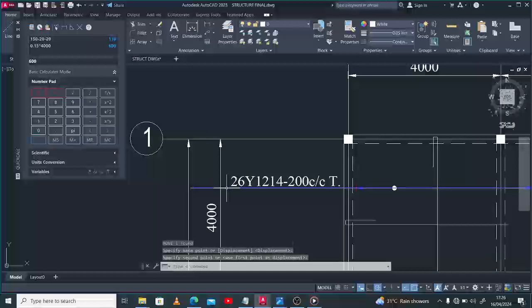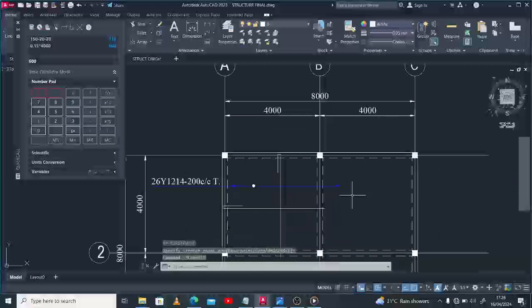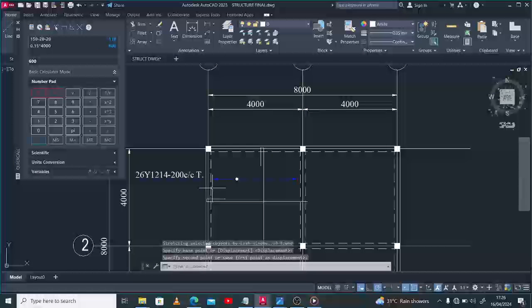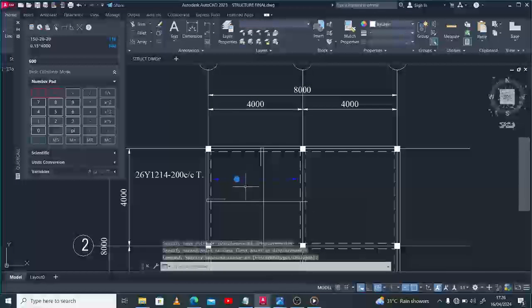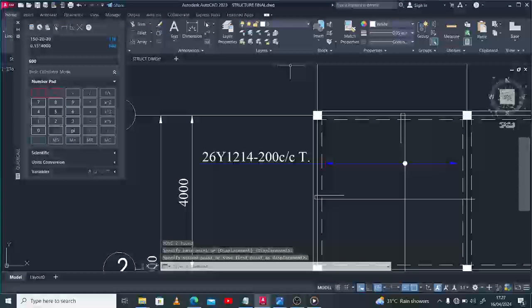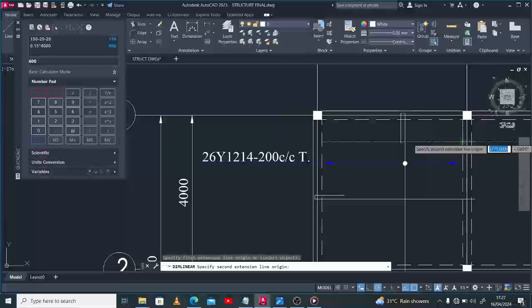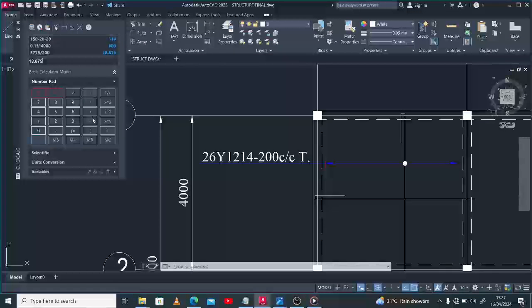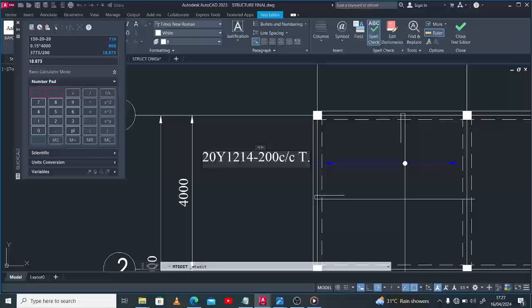So if we take this information, for example, it's going to span from there to there, from this place to this place. As you can see, that's telling of this vertical reinforcement. So let's assume that it's a 200 mm spacing recommended by the design, and the span here is 3775. What you just do is divide 3775 by 200, then you add 1. That's going to give us 20 Y12. You may name this 01. And this is a bottom reinforcement, not top reinforcement.